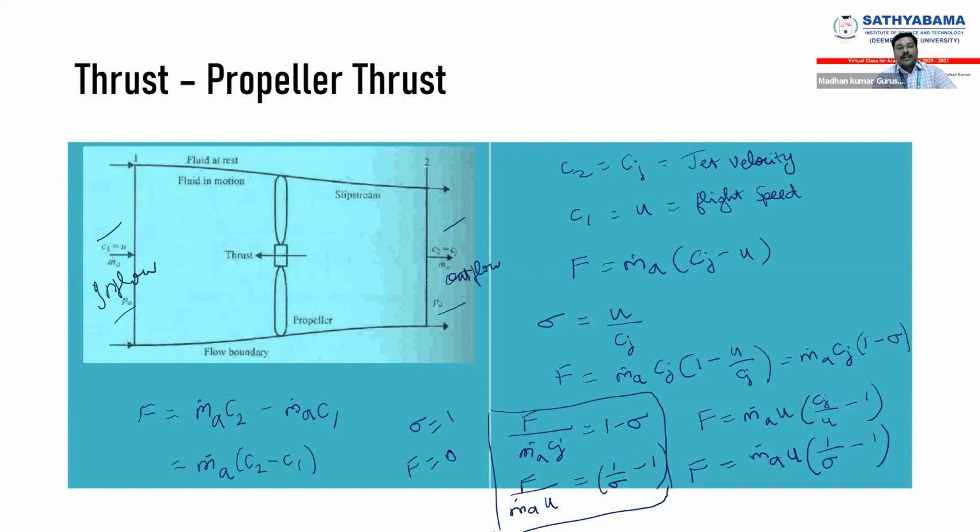And then, in order to achieve the highest thrust, that is maximum thrust, the condition is that you have to match the exit pressure with the ambient pressure. Here the exit pressure is PE, and the exit pressure should match the ambient pressure. At that time we get the fully expanded work done, that is, fully expanded thrust would be obtained, right?